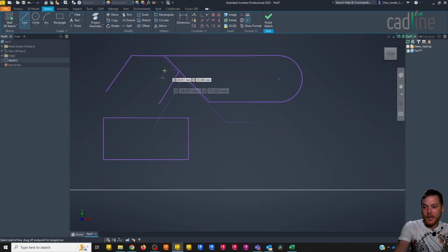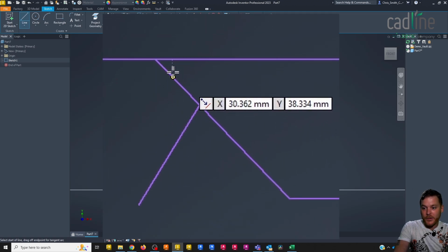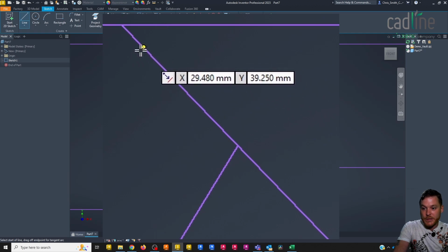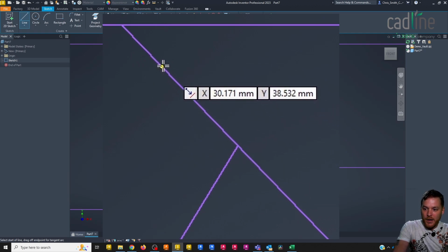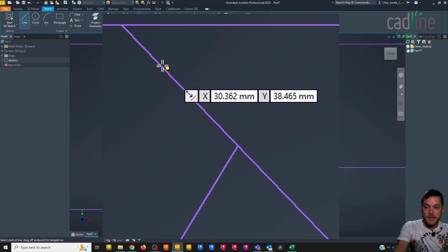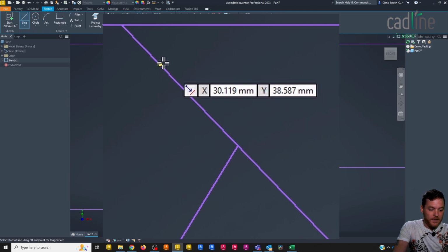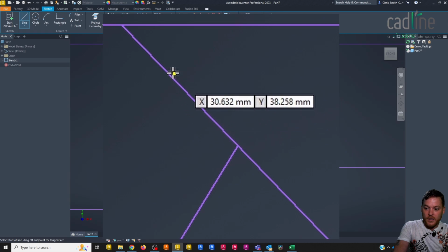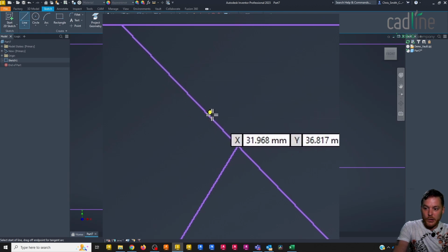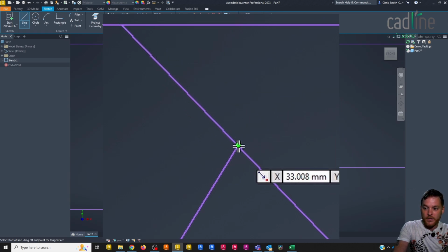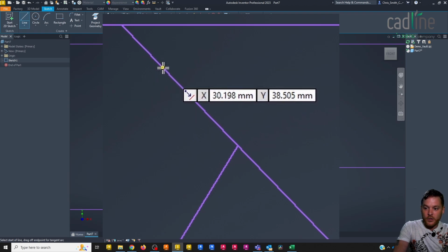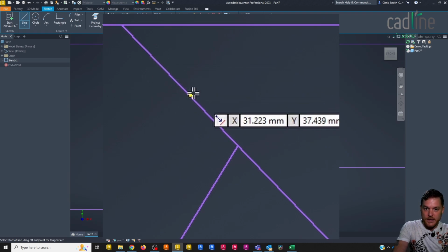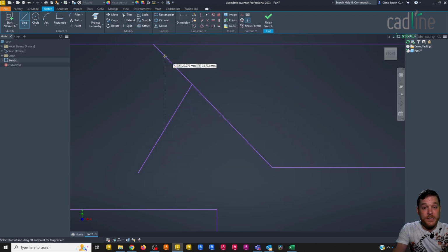Next, when we are drawing lines, you see it's trying to snap to some theoretical points up here. If I zoom in, you can see the projection lines coming up. I might want to start a line close to these lines, but without snapping to those points. So once again, if I hold Control, we notice that it no longer gives me theoretical points to snap to other than end points. Let go of Control, and we see those lines coming in. So if you want to, again, ignore those deferred points, just hold Control, and that selection option goes away.